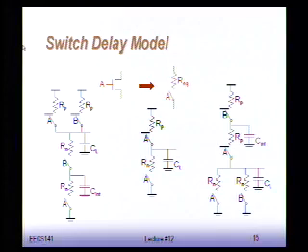So if I gave you a logic gate with transistor sizes, you would be able to calculate all these C's. And also you would be able to calculate all these R's, okay? So then the question becomes, given these R's and these C's, what's the delay, okay? And so we have seen this. This is an AND. Anyone has an idea what this is?